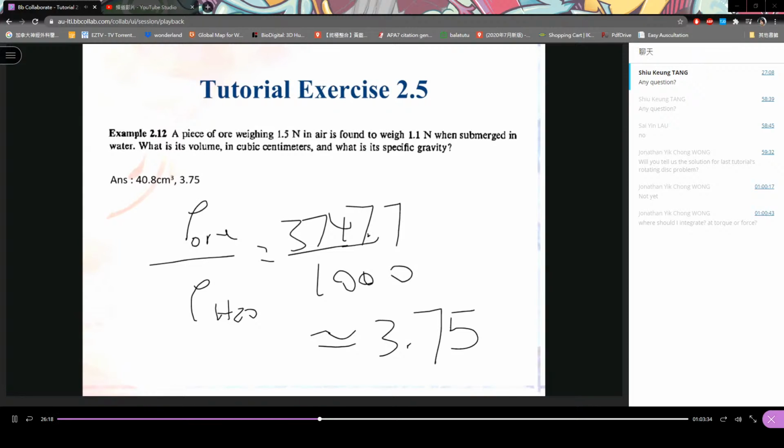Okay, so now this is buoyancy. Buoyancy force equals the weight of fluid displaced. In air, because the density of air is so small, we usually ignore the effect of the air density, right? Of course, if there are two fluids, then we have to take in the density of the two fluids as well when calculating the volume of the submerged object. Okay, now next we are going to deal with two really involved questions. So before going into it, any questions so far?